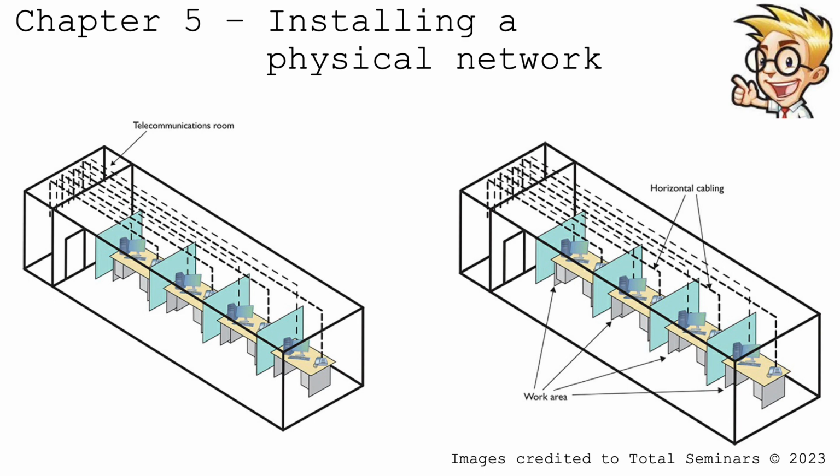Okay, so earlier I was talking about the telecom room or the telecommunications room. So all of your cables will run preferably horizontally, up and over, and go into the work area. So when it's finished, it'll look something like this, and that way we have 4 different desks or 4 different cubicles that have the same layout.